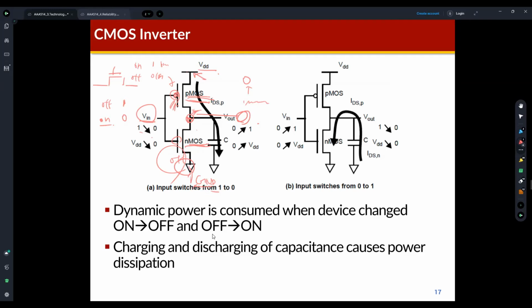So in this case, the PMOS is turned on, and this capacitor is connected to VDD. If the capacitor has a lower voltage level, electric charge flows from VDD to the capacitor, so the parasitic capacitor is filled with electric charge and reaches the higher voltage.